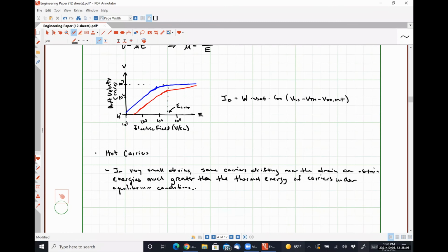But what if one of them hits a lattice vibration funny and fires up into the gate oxide? We start winding up doping our gate oxide and causing it to electrically break down, right? The oxide is a big neutral barrier that prevents current from flowing through the gate and influencing the behavior of the device. That's why we get that very nice and neat kind of switching operation. If we start effectively doping that oxide, what happens?